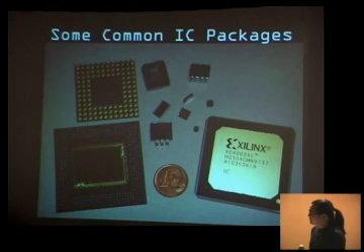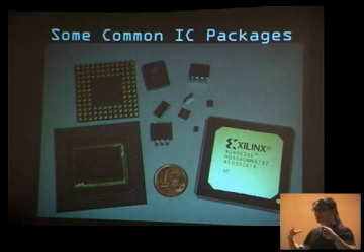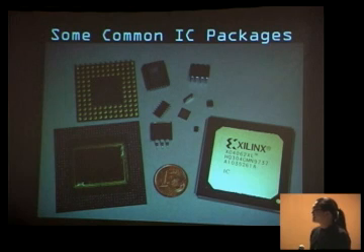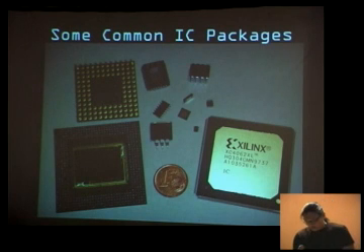So for these here, you have to be a little careful because a lot of times they have this metal pad on the bottom and so forth. So you need to look up the data sheet to sort of see what's on the inside. It's just not apparent. This little tiny guy here is also a chip. This guy's a single logic gate right there. And this guy, of course, is a Xilinx FPGA with a huge number of logic gates.